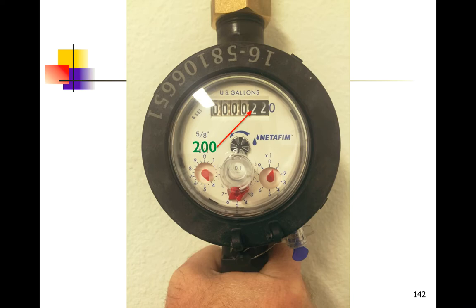With the 3/4 inch meter, there are two black background numbers. The first number with a black background is 100s, in this case 200. The next one is 10s, so it'd be 20. And then the 0 that's painted on the face of the meter is our single digits. For that, we read off the first dial, the red dial. Each digit on this one is 1 gallon, so a full rotation of the dial on the right will be 10 gallons.